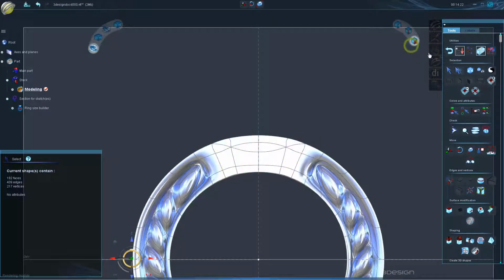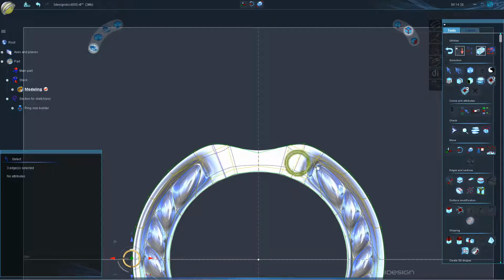And then selection mode under faces, we're going to remove these faces we just created. So another remove faces. Okay. And I want this corner to be a little sharper, so I'm going to chamfer it. So selecting, I double click to do an edge loop on both of those and do a chamfer. And just a small chamfer, 0.01 from the last one we used. We'll take care of that.